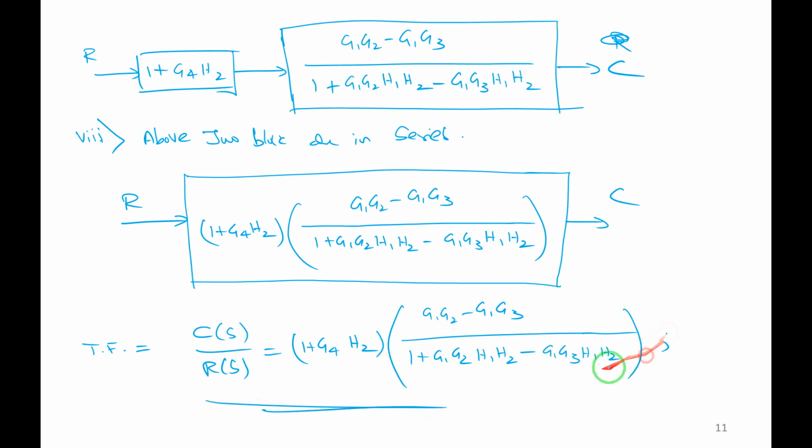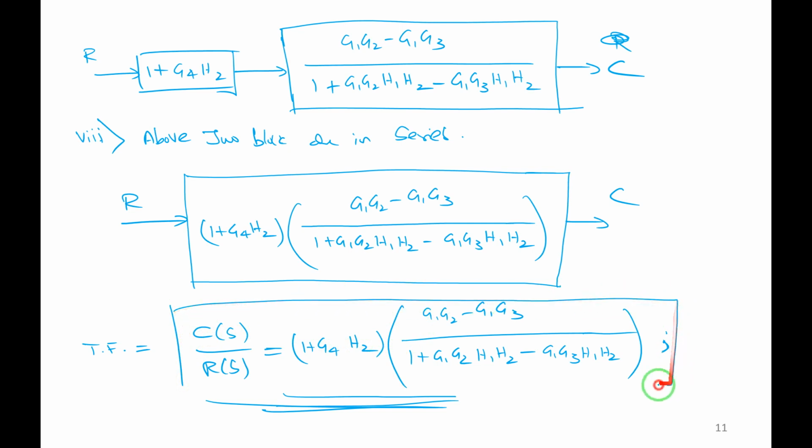Yes, this is the transfer function. So we obtained the transfer function by using the block diagram reduction technique. If you want to match this answer with the textbook answer, then you have to multiply and simplify it. But no need to multiply and simplify it; we will leave the answer here only. If you want to get the exact textbook answer, then multiply and simplify. So this is the transfer function by using the block diagram reduction technique.